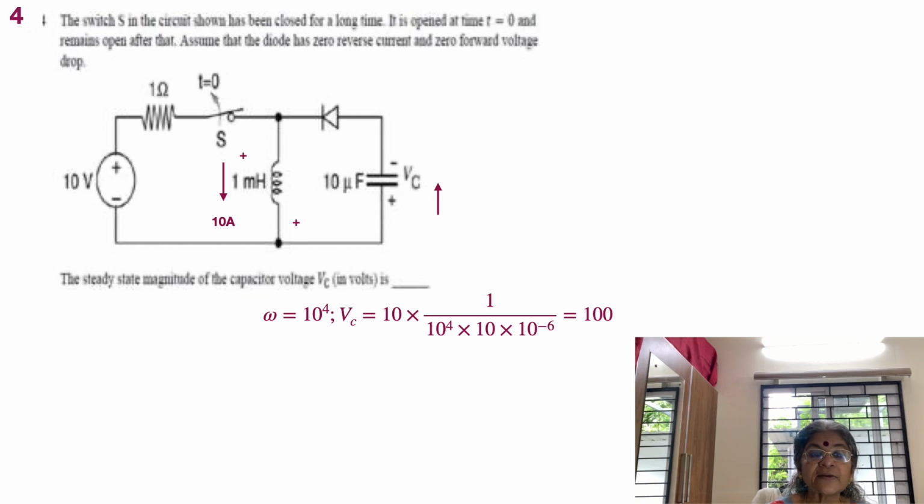So this current now flows through the capacitor and charges the capacitor such that the bottom terminal becomes positive and the other terminal becomes negative. At a particular time, the diode becomes reverse biased, and so no more current is possible. So there's a voltage build up across the capacitor and it cannot discharge in the reverse direction, as is obvious from the biasing particularities of the diode. So what is the voltage that is obtained here?